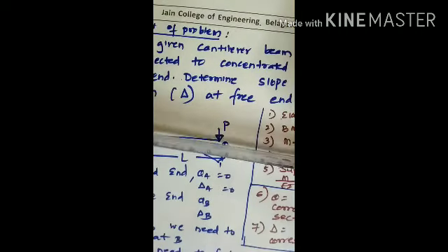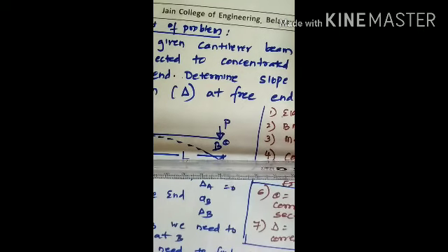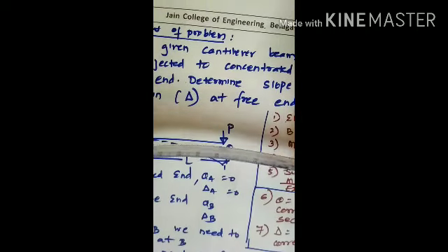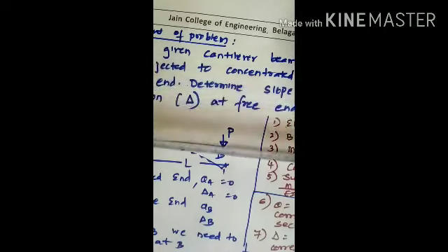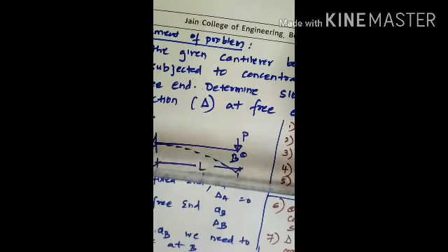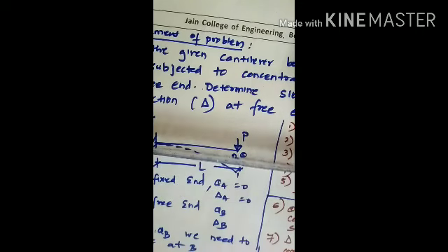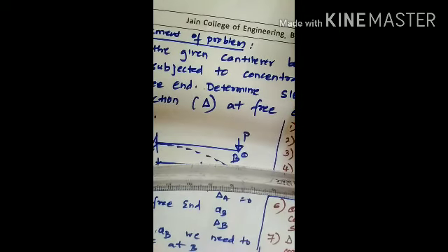Generally, bending moment diagrams for hogging are considered negative, and for sagging are considered positive. Here, if I apply a load P, the beam will deform in the form of hogging, and the hogging bending moment diagram needs to be drawn on the negative side. Whatever is above the top fiber of the beam is positive, and whatever points we note below the bottom fiber of the beam are considered negative ordinates. The same conditions prevail as per the graphical procedure. Here, since the beam hogs, we are going to draw it towards the bottom fiber of the beam.